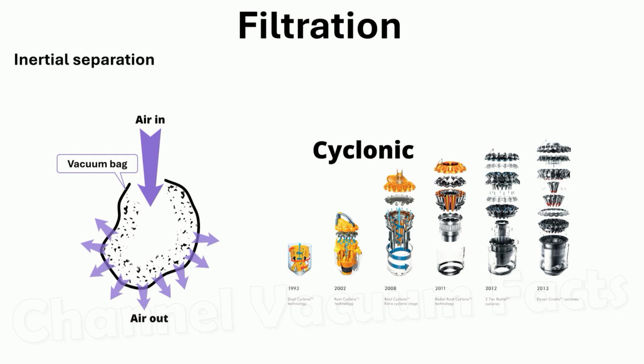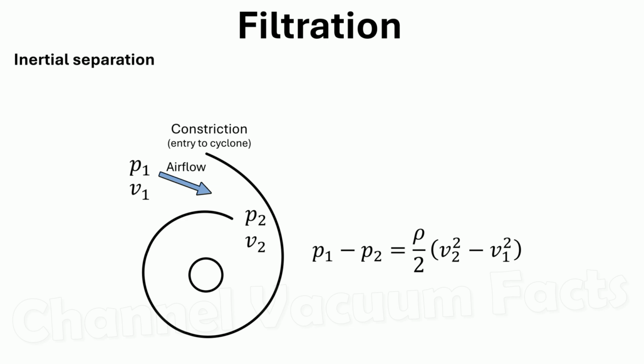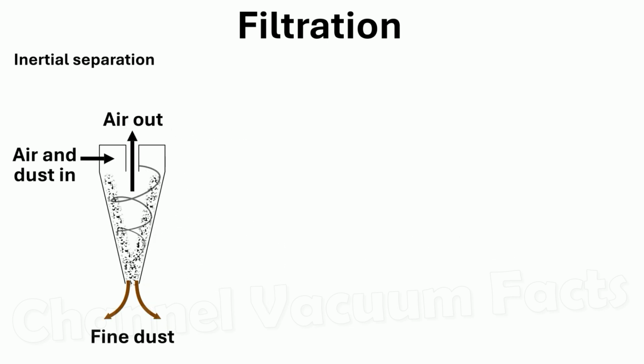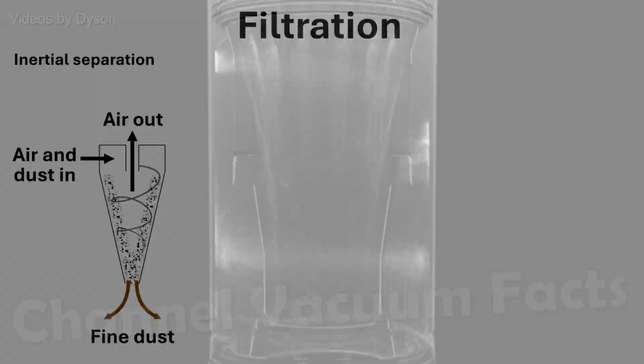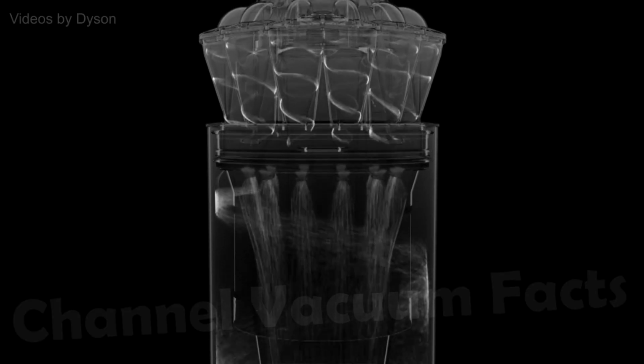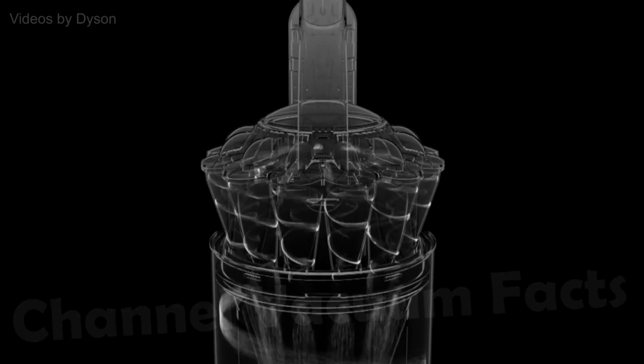Successor technology utilised inertial separation methods. The Venturi effect was employed within the primary dirt separator by constricting flow to dramatically increase airspeed and create a jet. Feeding this jet into a cone meant the dirt always changes direction and is therefore subjected to a centrifugal force following Newton's first law, gradually spinning towards and then out of the bottom opening.